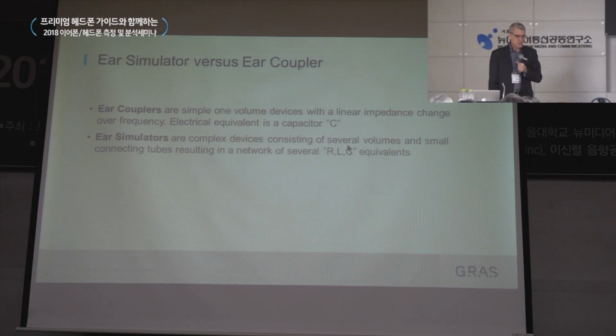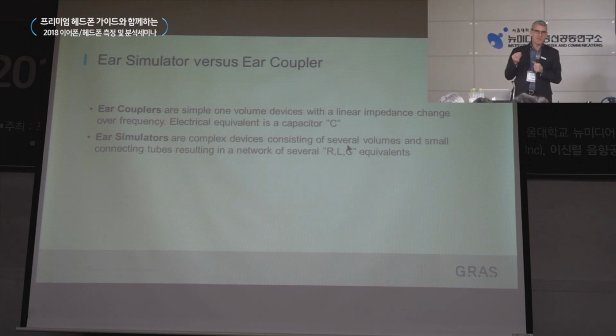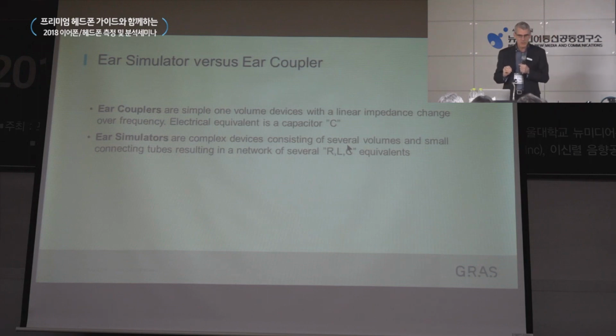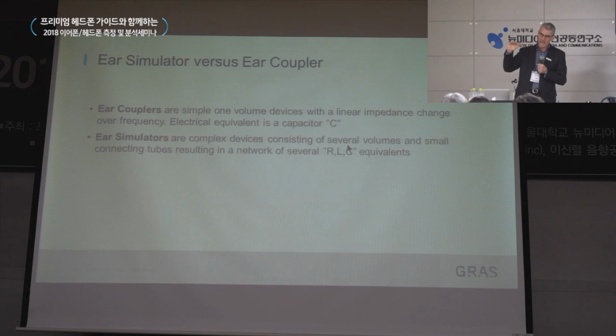So also, just to briefly explain, what is the difference between ear couplers and ear simulators? People often use ear simulators and ear couplers as if they talk about the same thing. But there is actually a small difference in the standards. Ear couplers are typically very simple couplers that are just a single volume, represented in an electrical model as just a capacitor, and typically have a very linear frequency response.